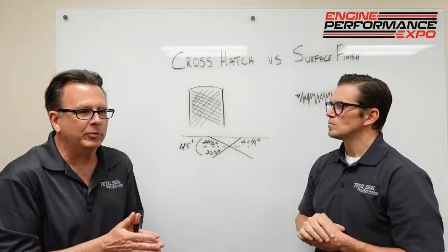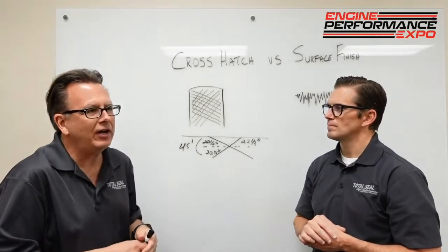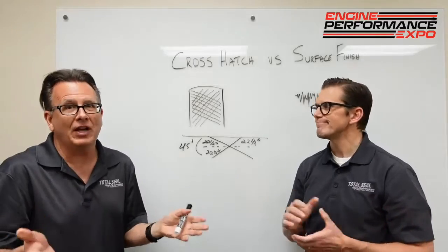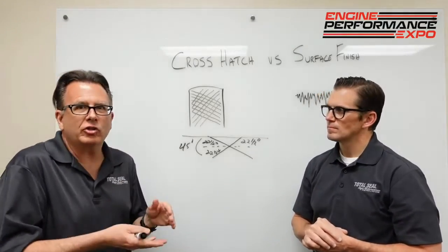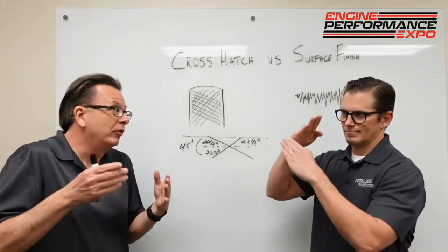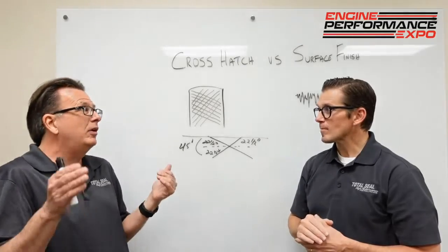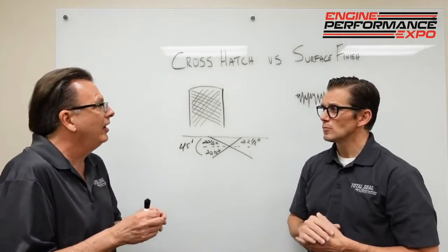I've had quite a few customers that have done a lot of testing on where that sweet spot is. And what we find, generally speaking, is the old 45 degree does a pretty good job in most applications. Yeah, it'll get you there. It'll get you there. Big bore, short stroke, high RPM stuff, we'll flatten her down. I can't say how far they've gone, but to get it into the high 20s to mid 30s is not uncommon. Seems to work very, very well.